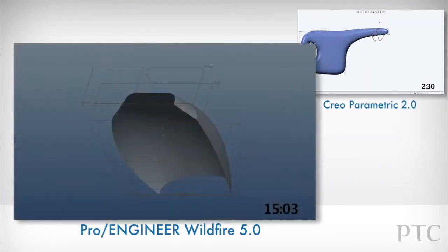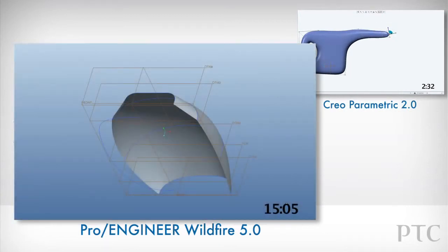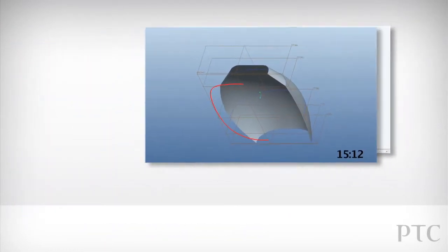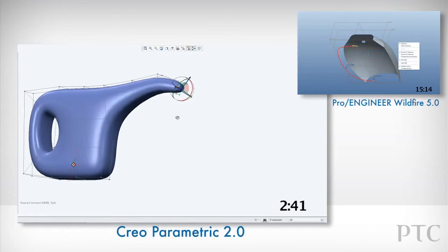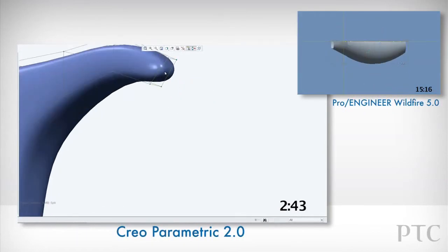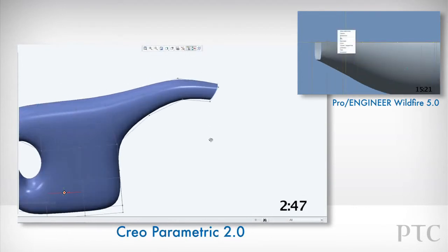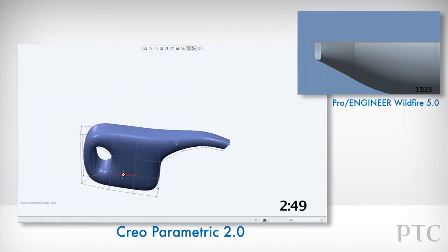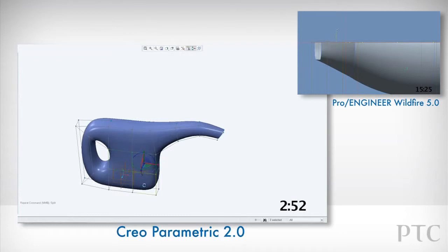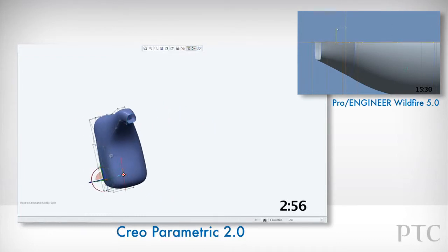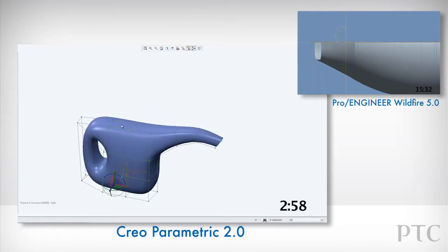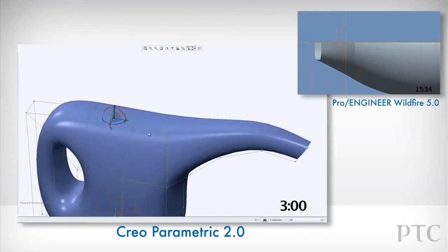Again, making changes like this in Pro Engineer Wildfire would have required a specific design methodology and having to manually select those curves and edit the surfaces individually. Once we're satisfied, we can also simply select and delete a patch of the surface to make an opening. Again, as we drag half the control mesh, you'll see that the part stays symmetrical.